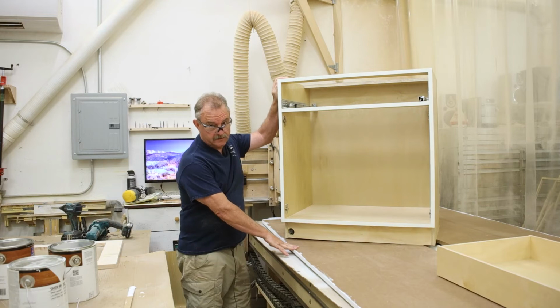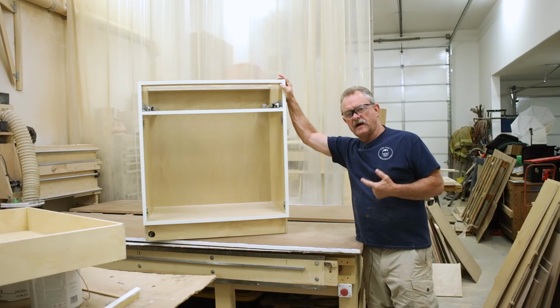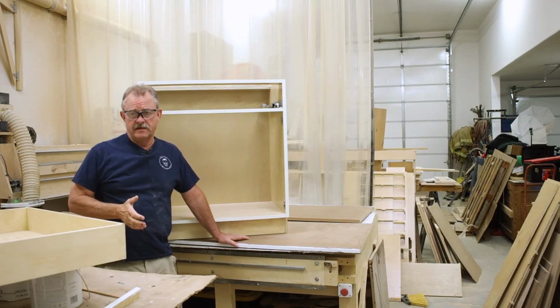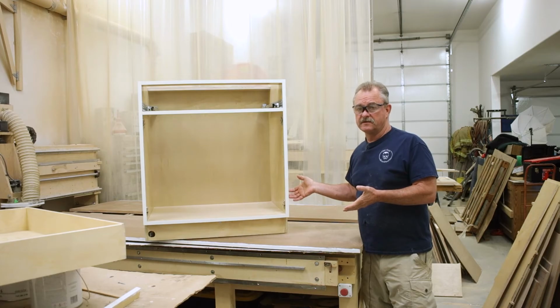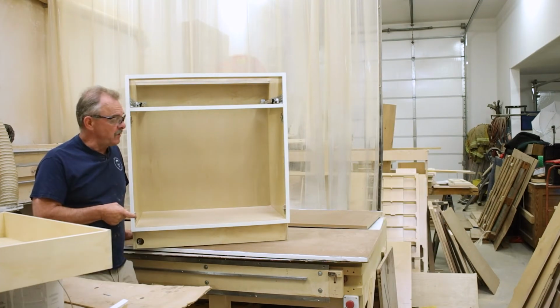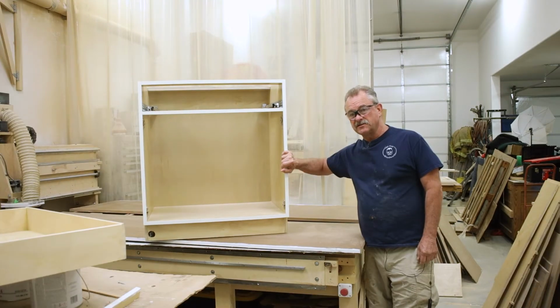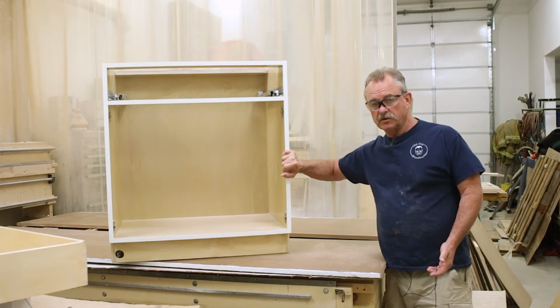Building cabinets on a CNC has a lot of benefits. I figure each sheet is going to take an hour to cut out. That's because I don't have a high-end CNC. A high-end CNC could cut a sheet out in about 15 minutes. But the efficiency comes in that while the sheet is cutting out, you can do other things like band, you can put the boxes together, you can prep all your doors.